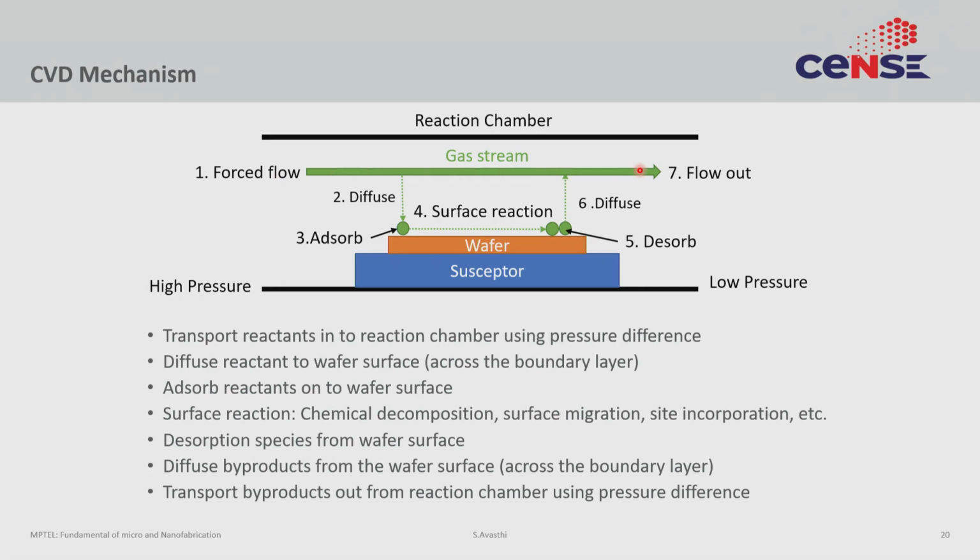We discussed some basics of fluid dynamics or viscous flow before. CVD is in the viscous flow regime. How exactly, however, this gas flows really depends upon the geometry of the reactor, and this is where the reactor design and various other aspects come in. Once you have figured out how the gas flows inside a CVD reactor based on your application, then you must also look at how the precursor actually makes its way to the surface. In general, that happens through diffusion.